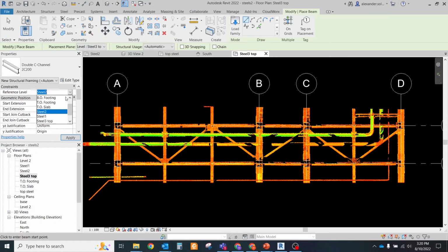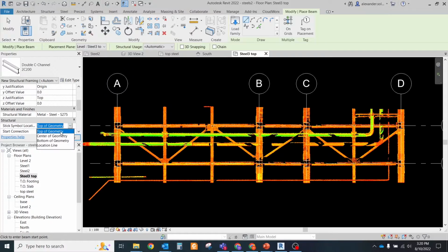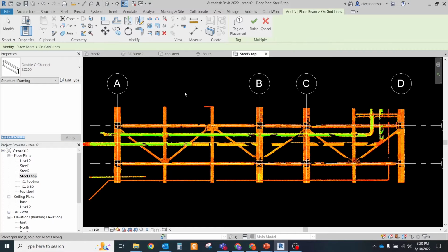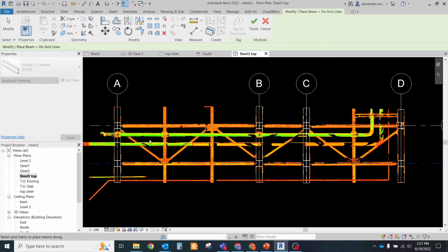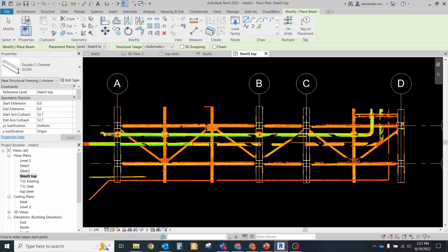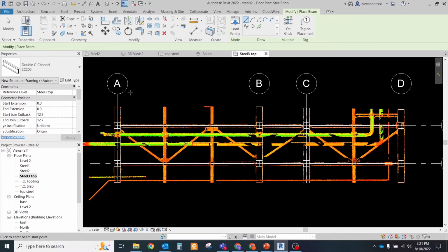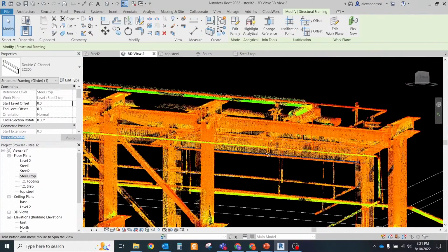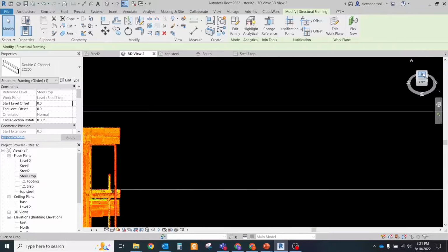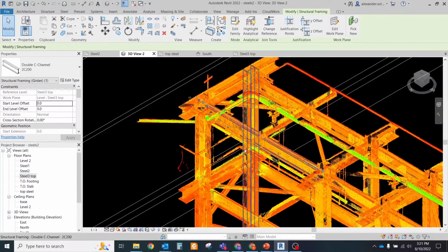It is suitable for work with straight walls and beams when all elements are placed on corresponding levels and on relevant axes, without leans and with right angles. But in real life it doesn't look like that. When we're working with point cloud, we are trying to create a digital copy of the real environment, but Revit doesn't work properly if all elements are generated with a small lean and with slight deviation from X, Y, Z axis.